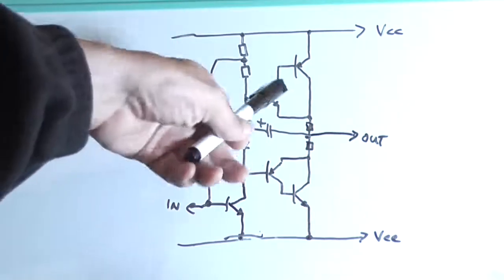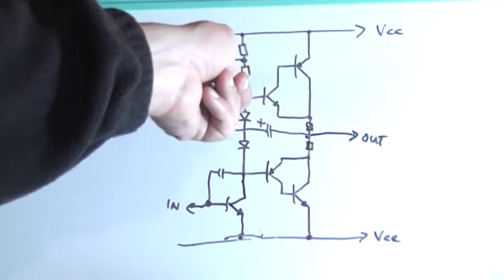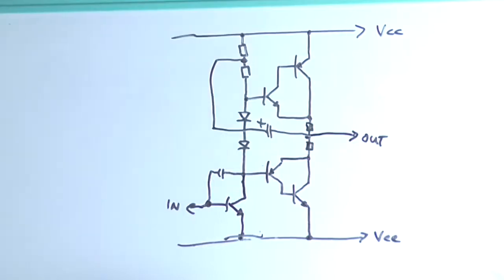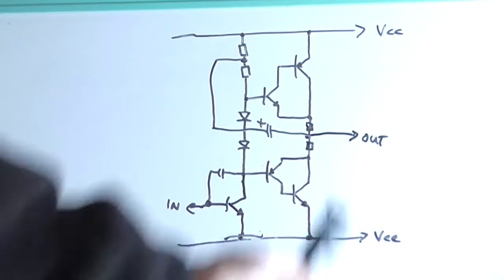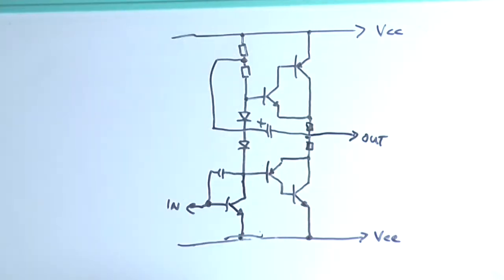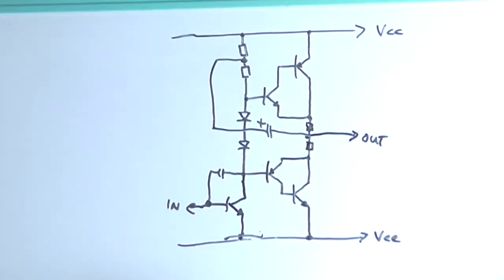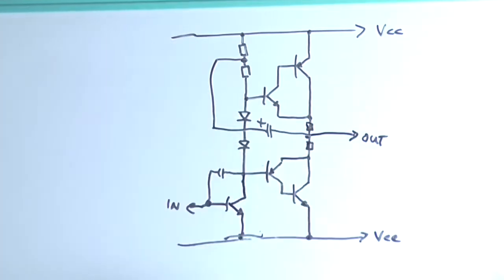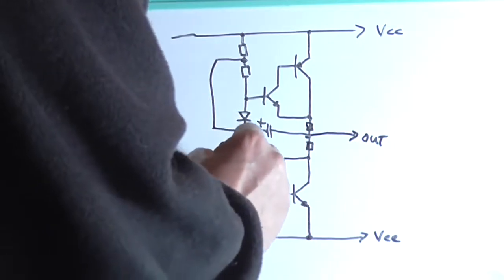But these are the things I'm going to try. One, I want to get rid of that potentiometer, that 50k that he's got in there to do the bias adjustment, and turn it into a fixed resistor. Plus I want to try out bootstrapping the output, as well as adding degeneration resistors in the collectors, or the common emitter points here, as there should be. And what we're going to do is, without the VAS obviously, I'm going to test this output stage. So for clarity, I'm going to now remove the VAS.